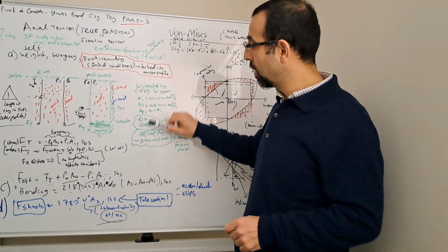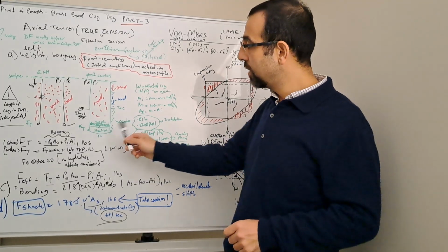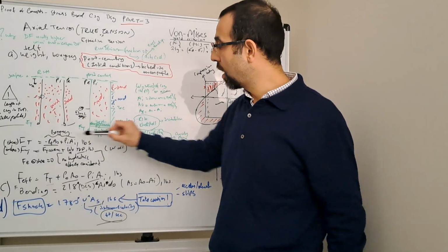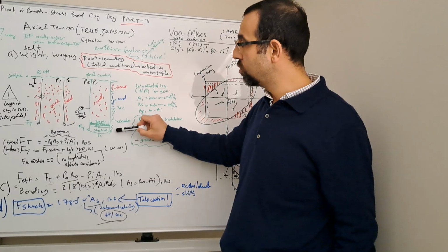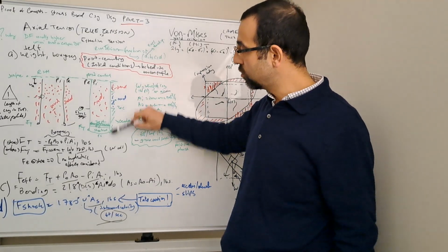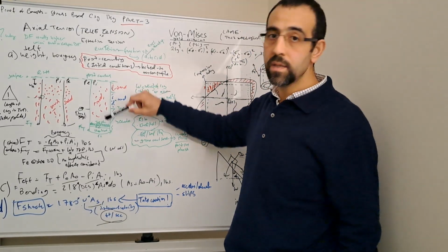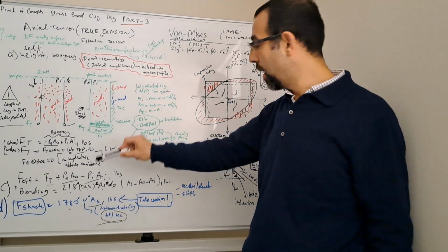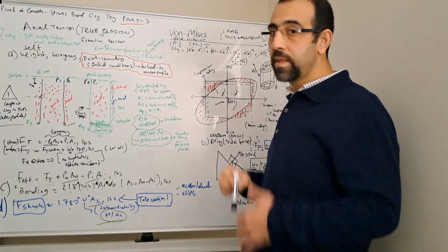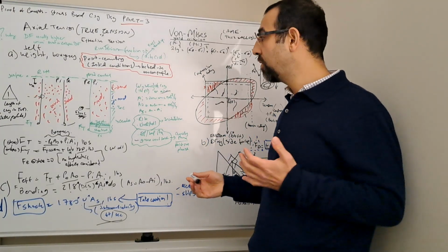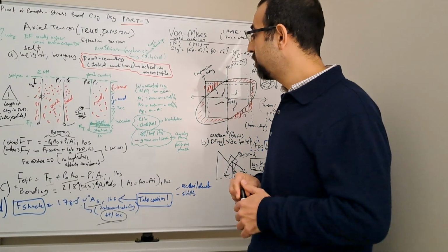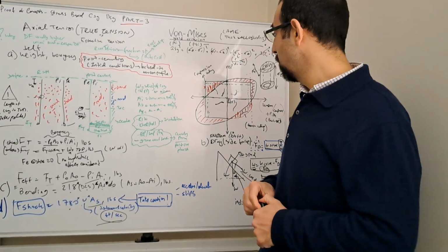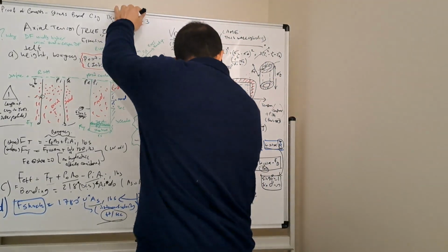But until now, we could calculate the true tension at the shoe, true tension at the surface, and true tension anywhere inside the casing string by accounting all the other elements, and then come up with a design factor rating of the pipe. Okay, so let me go to the second page.